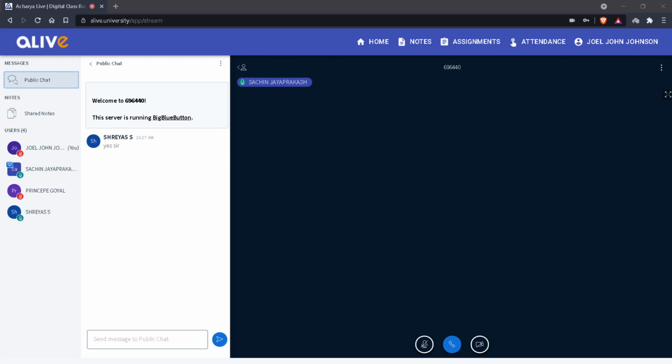and this one is offset on surface. So let's assume I select these. I select some curve which is on the surface, and in that case this particular option will be enabled. Or if you have drawn a 3D surface already, and on top of it you have drawn some curves, and you are offsetting that, this particular option will be enabled. Instead of using the other option, we can use offset on surface, so that it fits exactly on the surface.